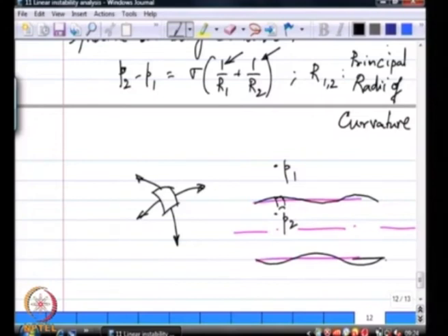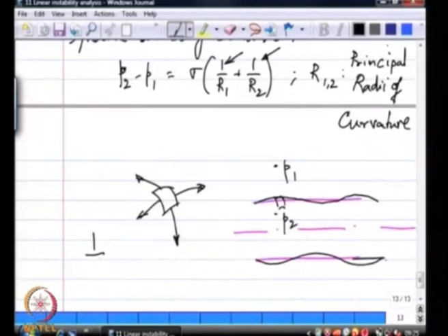That is for a very general free surface. But if I am dealing with a free surface that was originally cylindrical and I am only going to retain terms that are order epsilon or order eta in the perturbation quantities, then those quantities are order eta. So, in that condition the radii of curvature are in the coordinate directions. So, you have a radius of curvature in the r direction and you have another curvature in the theta direction, and that essentially comes to